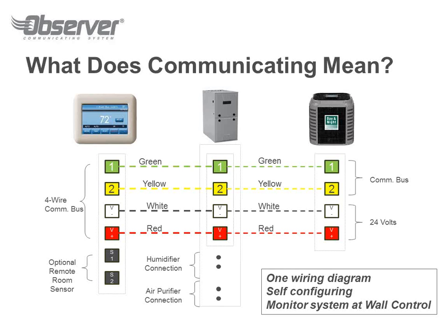So you have those same 4 wires that go from the thermostat to the furnace, then go directly out to the outdoor unit as well. Same kind of deal. White and red are 24-volt power, and green and yellow are the communication wires. So the thermostat talks to the furnace talks to the condensing unit. If the thermostat wants cooling, it'll tell the furnace to turn on the fan, tell the compressor to come on outside. Everything's happening over those same 2 wires.